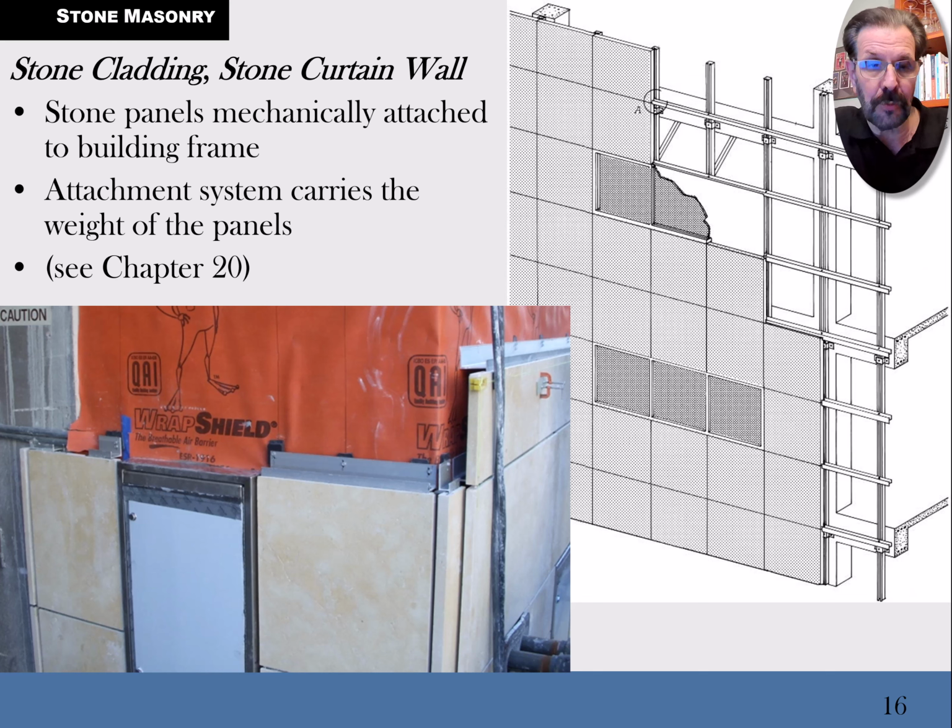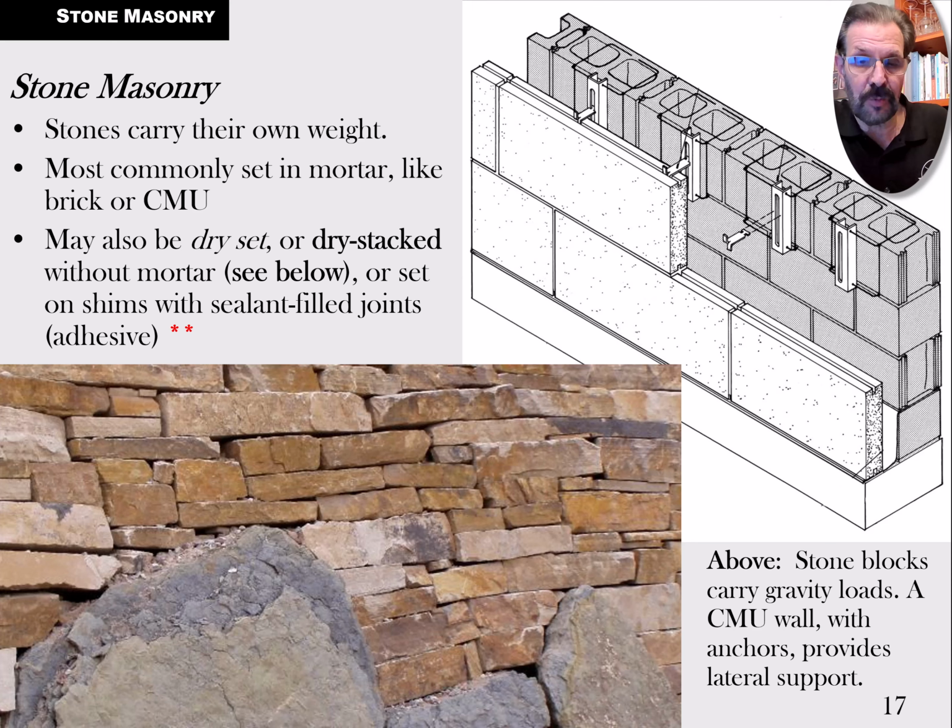Stone masonry in other fashions, this is what we call dry stack, and I was searching for that term back in chapter 8, and I just forgot it for the moment when I was in the heat of battle, on the earlier video. But stone masonry, if it's dry stack, it looks not as junky as this. They've got some kind of concrete chunks down here they're using. Possibly that will be hidden, and that's why they're able to use it there. But in building walls dry stack, any kind of dry stack walls or columns or anything else, you just don't see any mortar. There can be mortar, but a lot of times in modern construction, it's not mortar anymore.